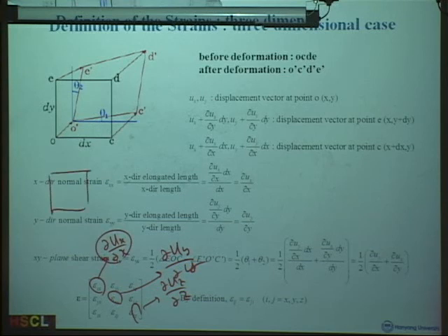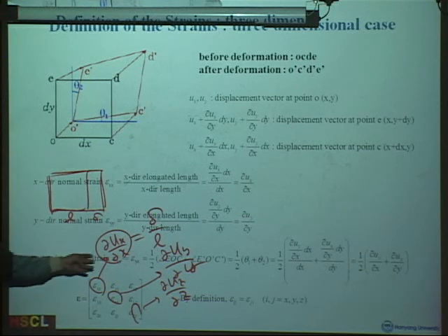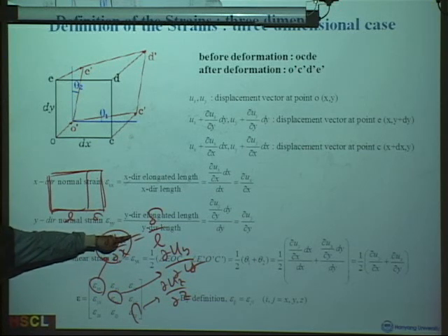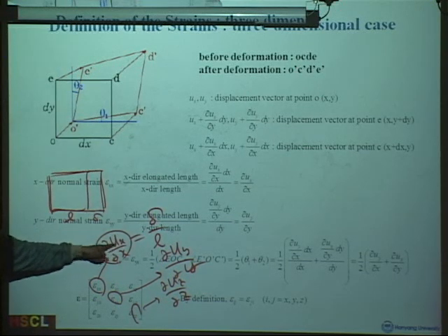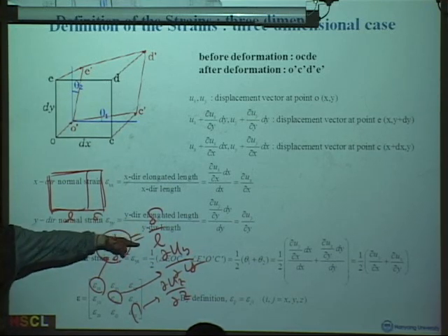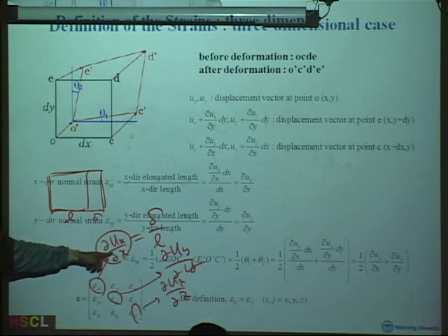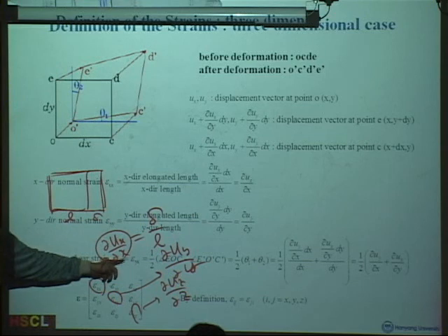Let's say we have a rectangular cross-section like that, and if we extend this much, this much is simply delta, and this is L. Delta over L is the axial strain, right? Delta is a relative displacement, and x is the L. Delta over L is simply a simple version of this derivative, in x, y, and zz.